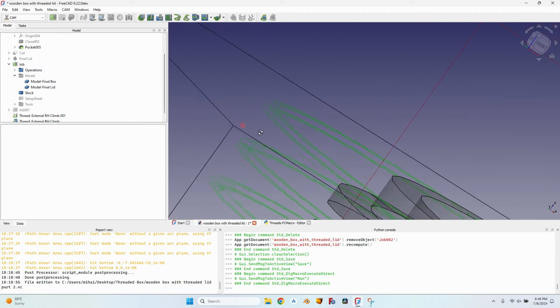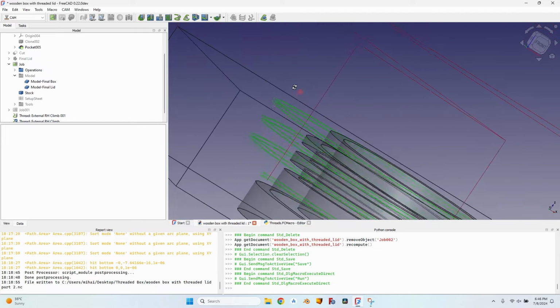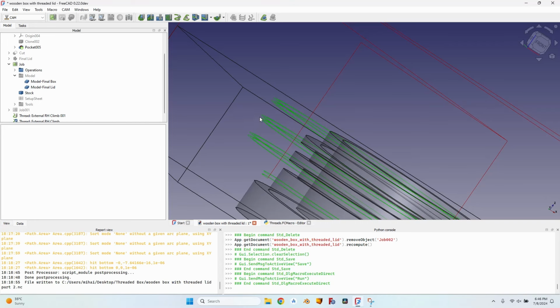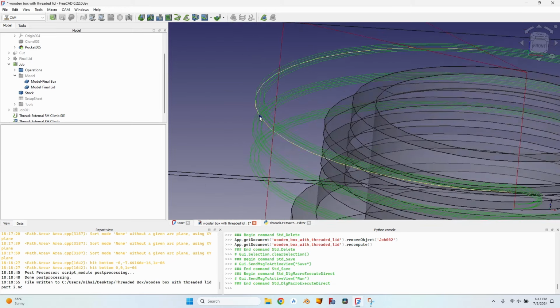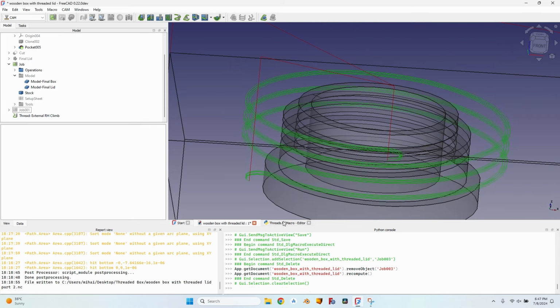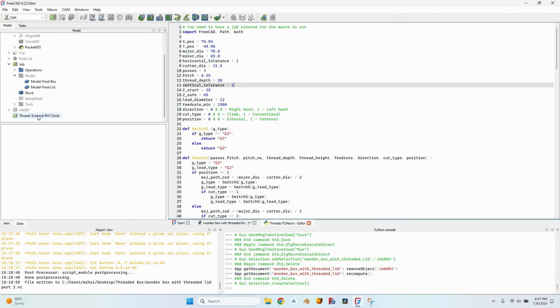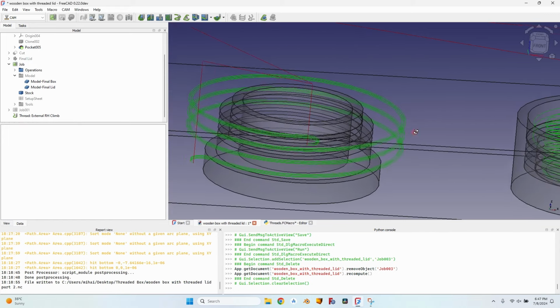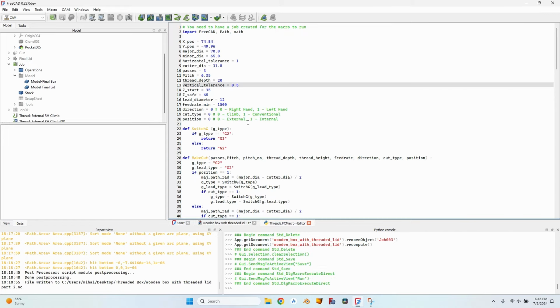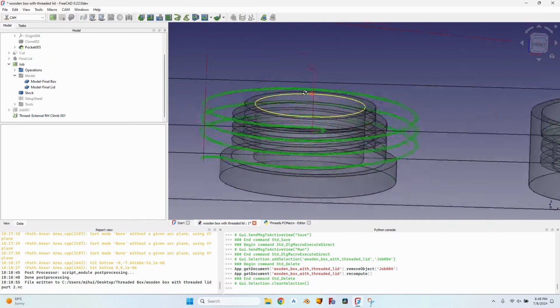You can see I have two passes on the Z-axis. The vertical tolerance will make another cut slightly higher than the initial cut. This will result in wider channels here for the thread to fit a little bit easier. Adding these tolerances might help a lot matching the pieces at the end. You have to take into account that after creating a new operation, you have to delete the previous one. This macro won't delete the one before. I will leave these tolerances of 1 millimeter. On the vertical I will write a 0.5, because the 0.5 for the outer and the 0.5 for the inner will result in a total tolerance of 1 millimeter. One final run of the macro, delete the previous, and this is the final path for the thread.